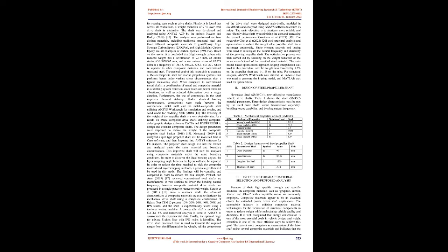For ease of understanding, modeling is done with Catia software and analysis is done with Ansys 10.0 software. When compared to a typical steel drive shaft, the composite drive shaft saves weight by 81.67% for Kevlar/epoxy and 72.66% for glass/epoxy.